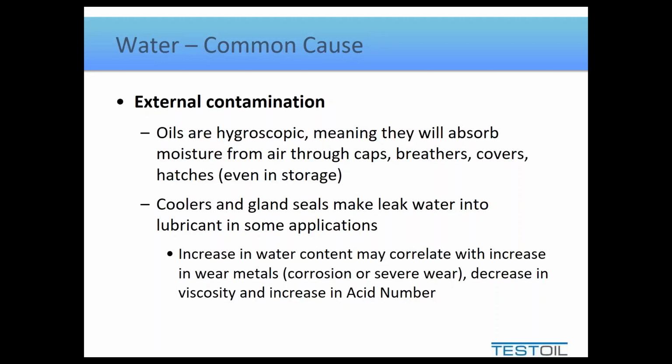Quick way of doing that is to look into your cooling system if it's got a reservoir of any kind and see if you've got oil floating in there. If you do, then clearly you've got a two-way leak.